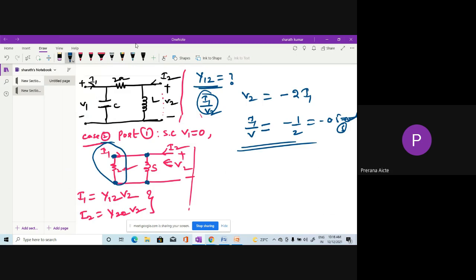Hope you understand how to calculate the Y parameters for a given network in a simple manner by using current division and the two-port network equations themselves. We are not approaching any mesh and nodal analysis here to solve these questions. For the sake of simplicity, this method is suitable and sufficient. No need to follow one method for every student.